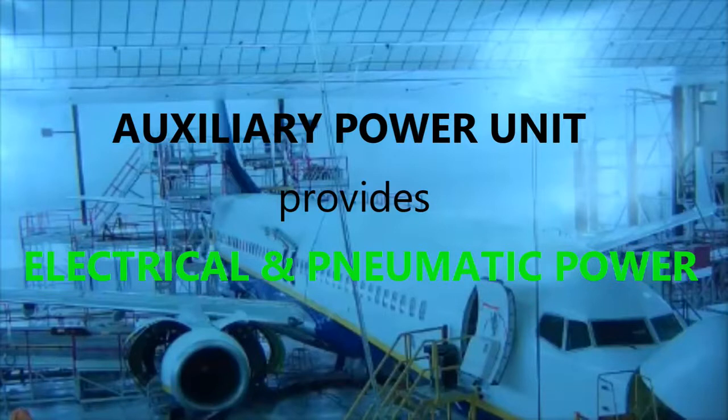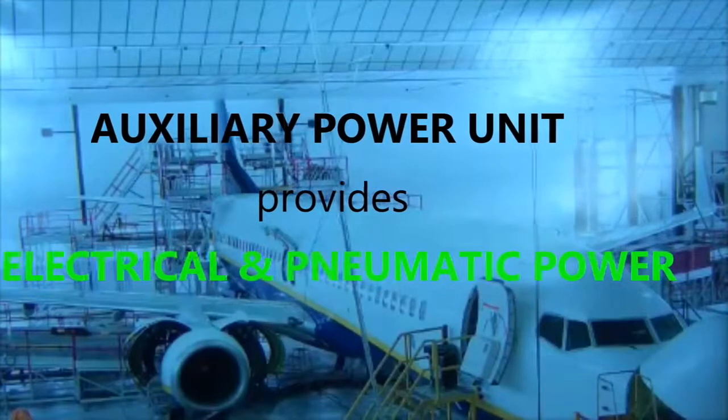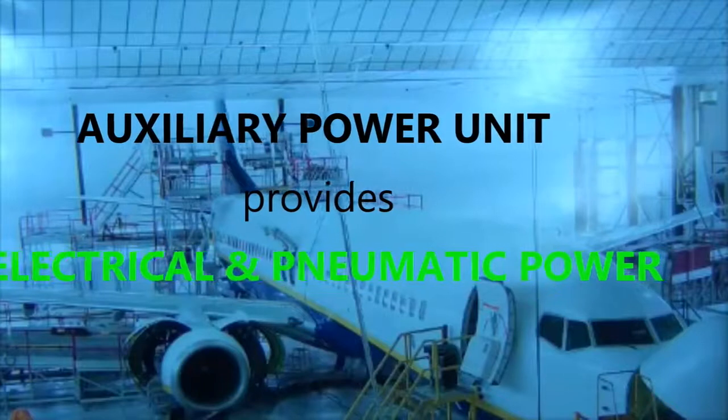You have 16 of these inlet guide vanes that are moving, with an actuator that's operated by a gear train. So there's 16 of those. Okay. Remember, bleed air is predominantly here for main engine start.